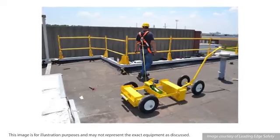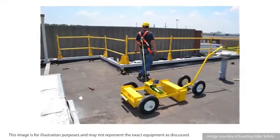The anchors that we use the most depend on the job we're at. I just finished an indoor gas station with 70 pump heads and 16 car washes. That was only 2 stories tall. There we used a mobile set of tie-off anchors, which actually rolled around and had a weighted system in there, so it worked off friction. We could take it to the edge and then people would be tied off that way.